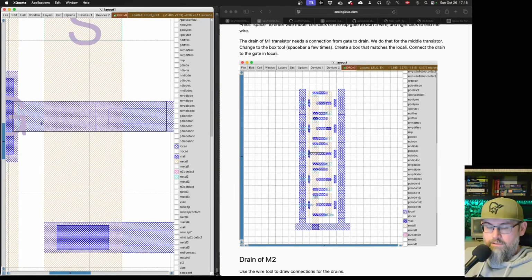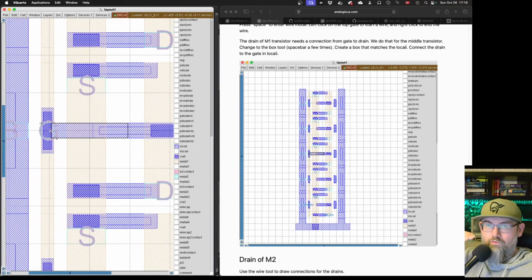The reason I want to do it in local interconnect is that I want to connect the drain to the gate in the lowest possible level, because every time you add a metal layer, there is what's called a chemical mechanical polish that happens on the wafer. And this chemical mechanical polish has the tendency to induce charges into the metal. Now those charges, if they're picked up by the gate, could actually cause damage, because you can break the covalent bonds, like, well, in an oxide, which is an amorphous or random distributed collection of silicon and oxygen atoms.